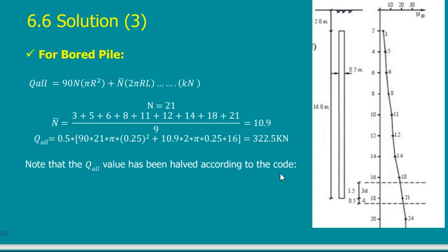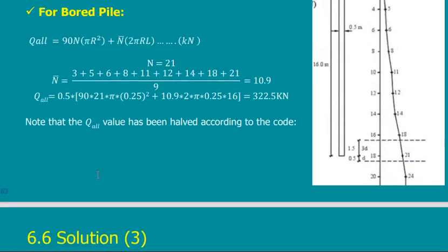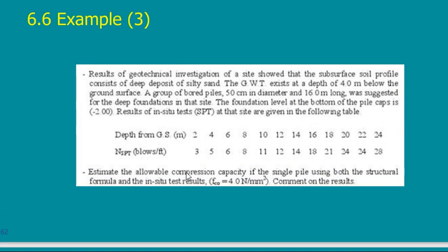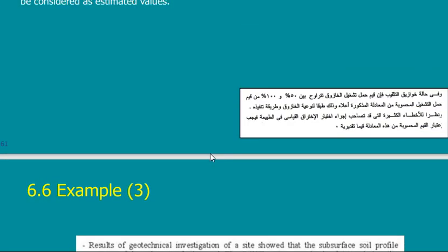If by chance you need the ultimate for any reason, then you will have to take each term and multiply it by its corresponding factor of safety. As I told you, in this example we have many things that I want to stress. The last thing I want to stress is that this equation is mainly used for driven piles.